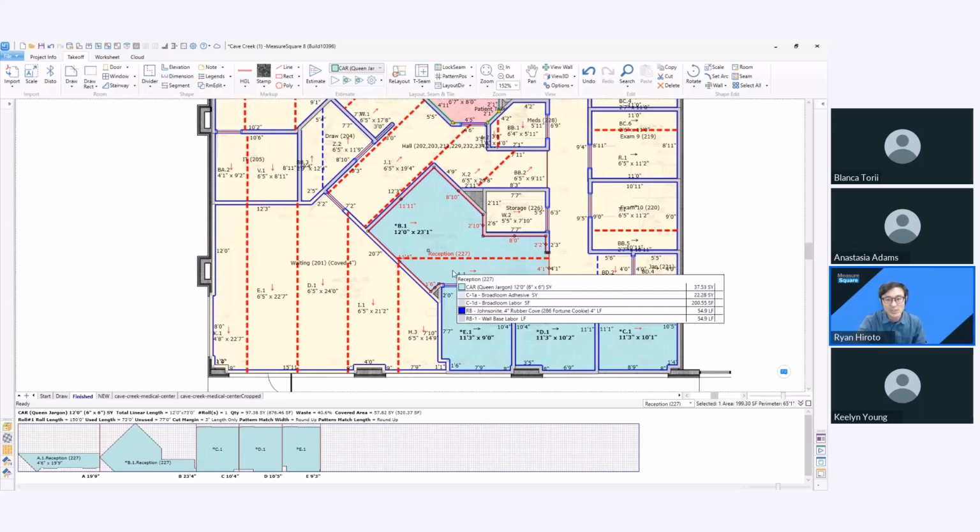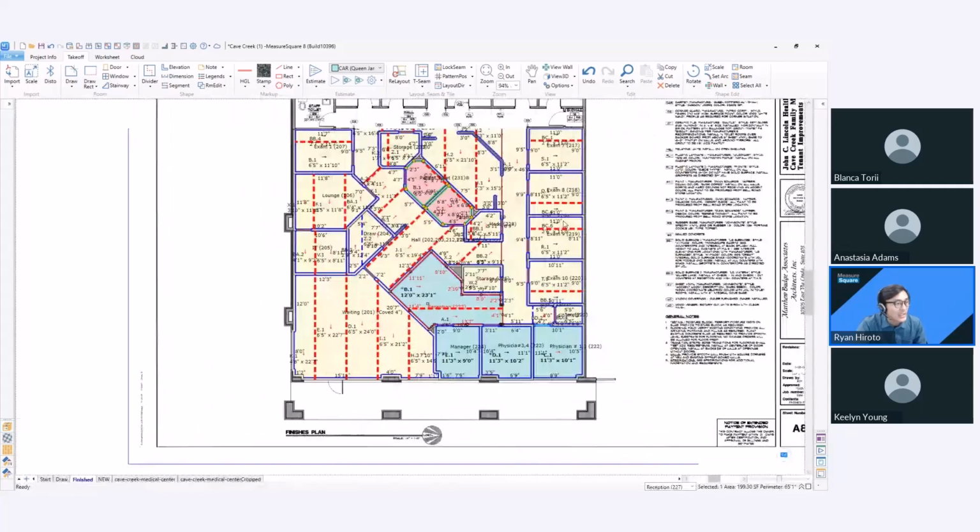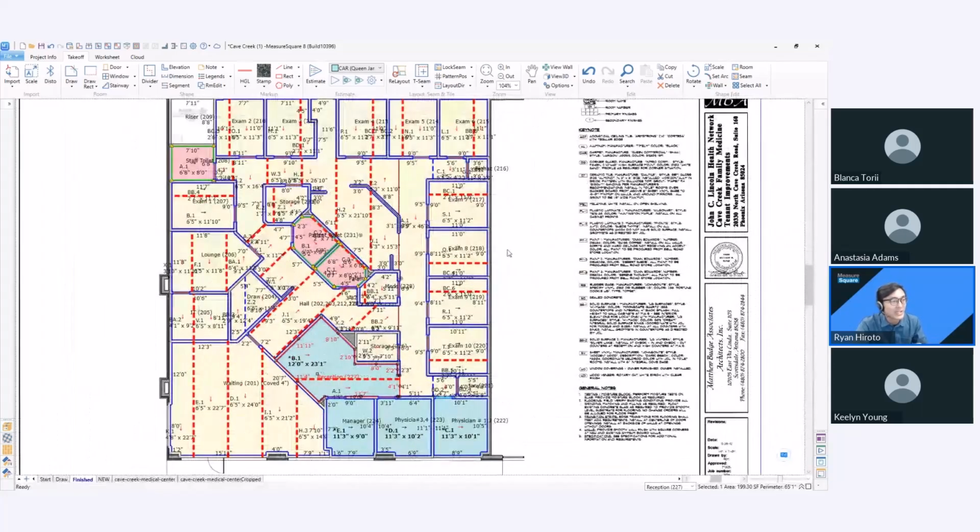in a future session. And another thing we can do after we've switched the seams here is, once we have our seam layout the way we want, we can lock them into place. We have 3 places to lock our seams. We have the seam lock up top here. We also have, under shape and edit on the top right corner of the screen, the room lock and seam lock. So you'll want to make sure that all 3 are locked.